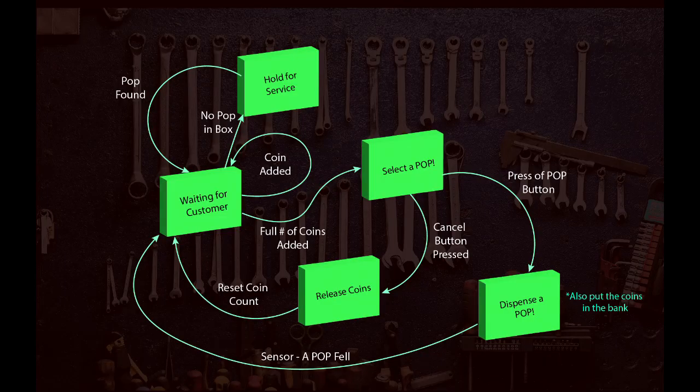This sort of design diagram can aid us in designing the machinery and logic inside systems like the vending machine. We can be as descriptive of each state as we want. The behavior should not change inside each state without an input or a transition criteria. What stops the motor in the machine from pushing out too many cans?